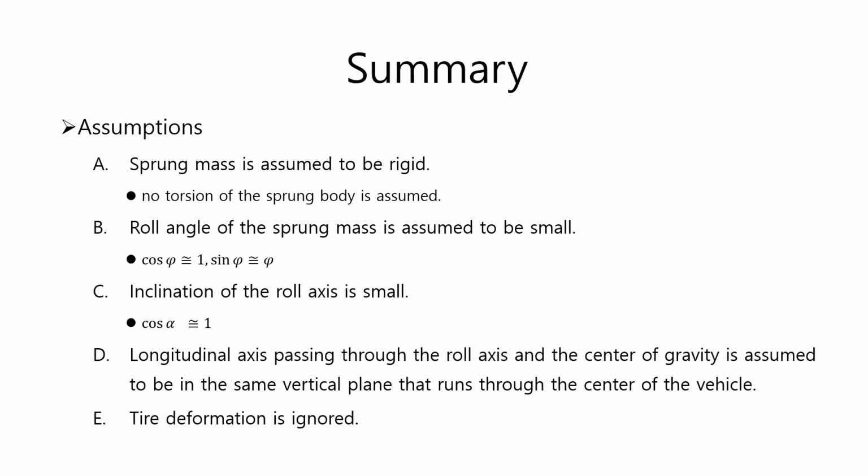However, here, if the suspension stiffness is too large compared to the tire stiffness, the suspension displacement becomes relatively small and the tire deformation becomes relatively large, so the tire deformation should not be ignored. In this case, the tire deformation should be considered.